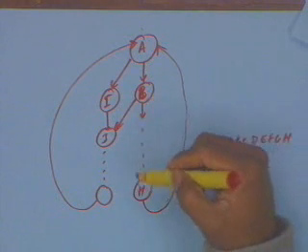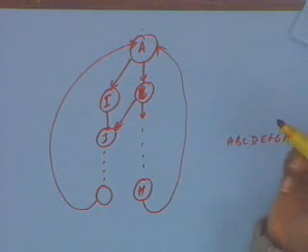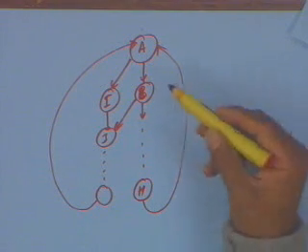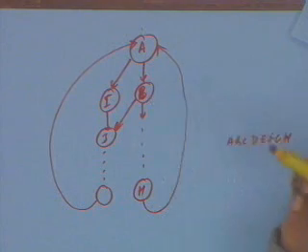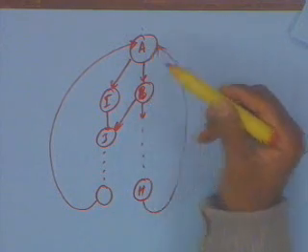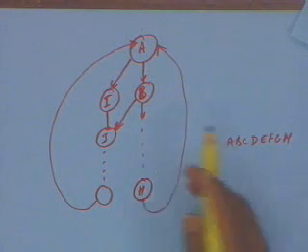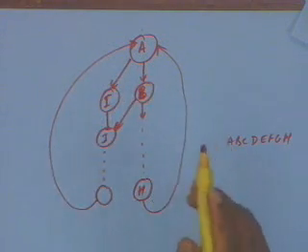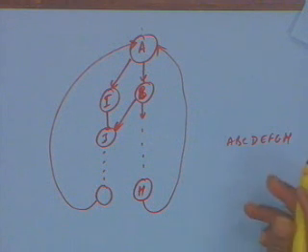That's important, because these 8 bits correspond to one character, and after 8 clock pulses I should again come back to this and look again. So when I am doing a design like this, for looking for the pattern of 8 bits, I don't need a separate counter.